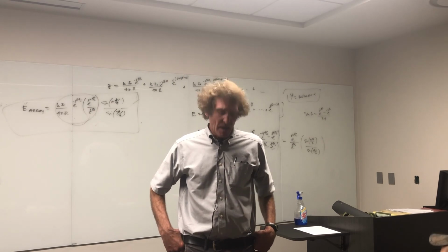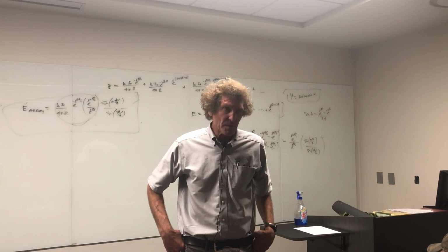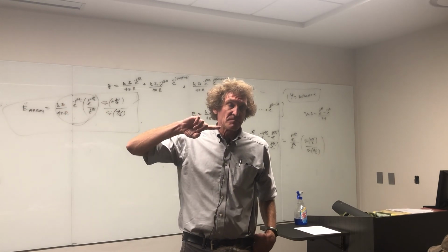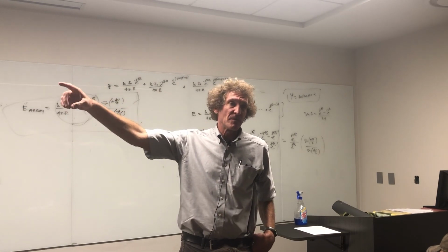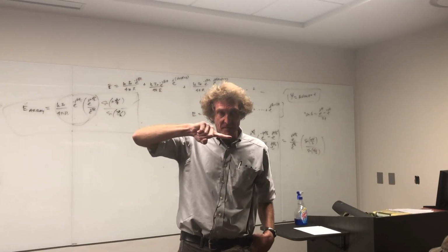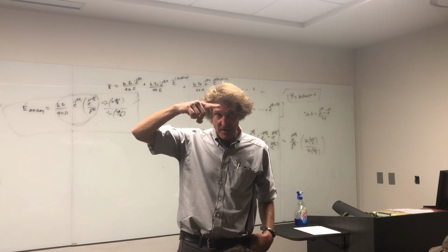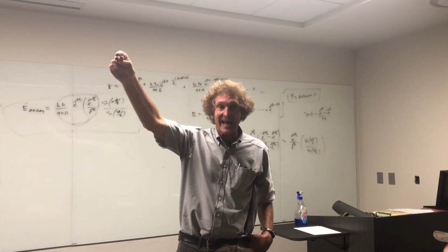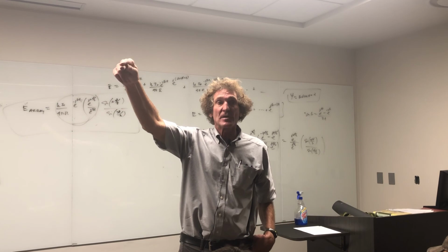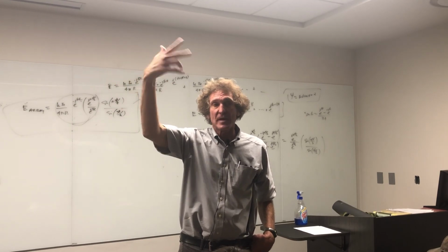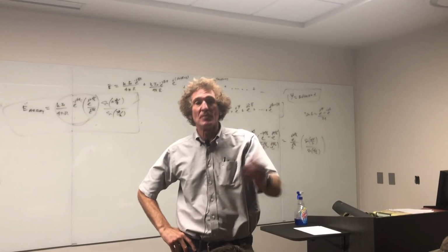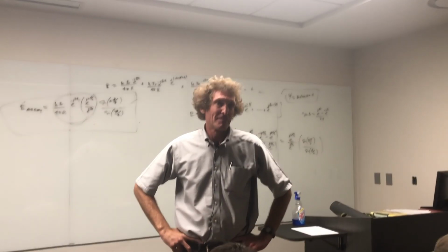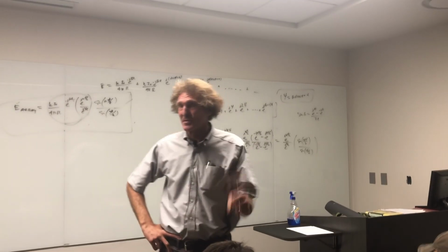That was for optical transmission, when we did the numerical aperture of a fiber optic. We had to come in at a certain angle, then it bends, then it hits, and that angle between the cladding and the fiber has to be the critical angle for total reflection. That was where we got that half angle thing from. I'm not testing you on that. No optics.